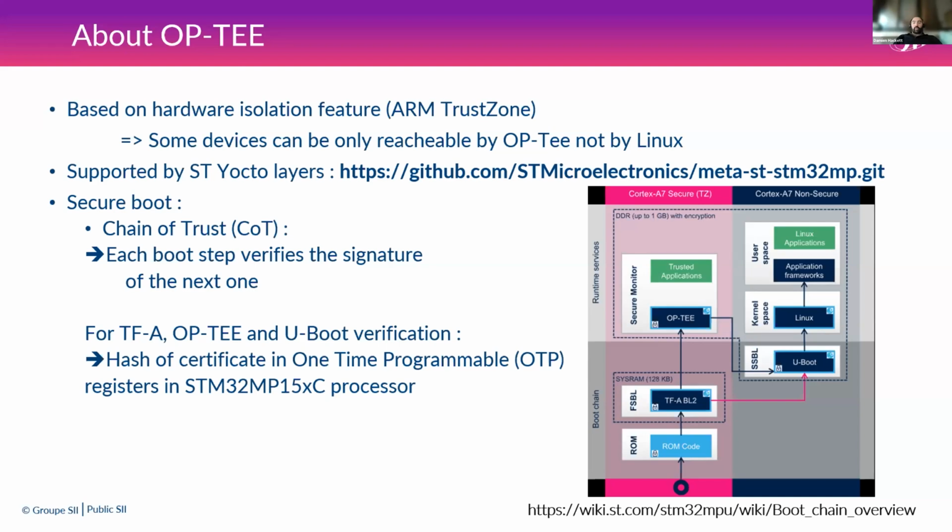We cannot have a malicious OP-TEE or malicious U-Boot. It's all signed and checked, and the keys are stored in the one-time programmable register. For the project, we use the STM32MP15 processors with C options, enabling the secure boot capacity.